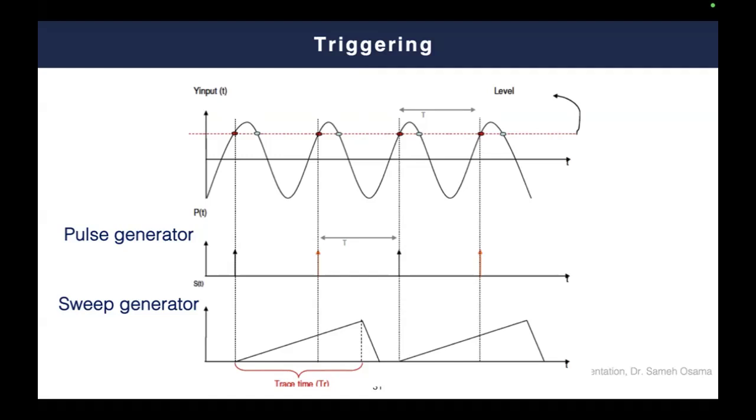What if we would like to measure the exact phase of a signal? Here, we should start our sawtooth signal in this point. So instead of starting the sawtooth here, you should start it here, so that it captures the real start of the signal, which is the real phase, which is -90, for example, in this case.